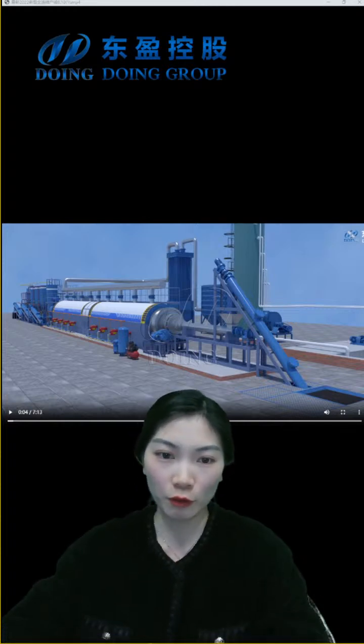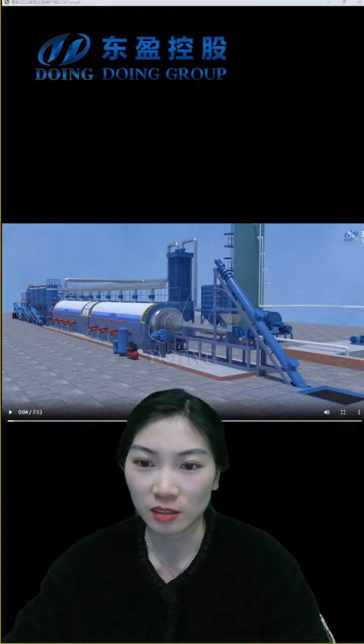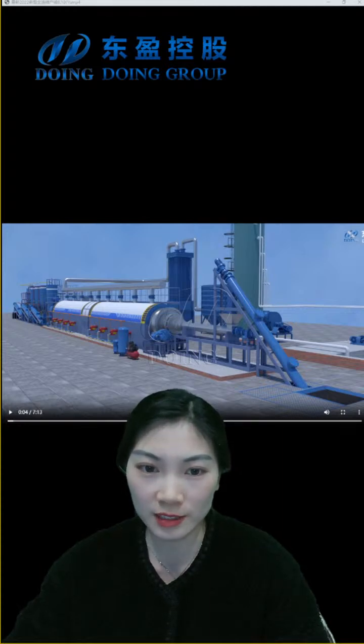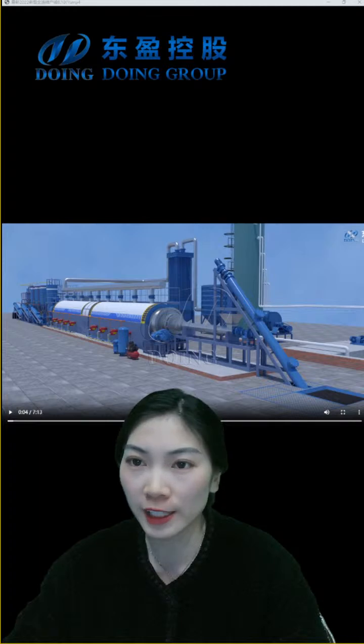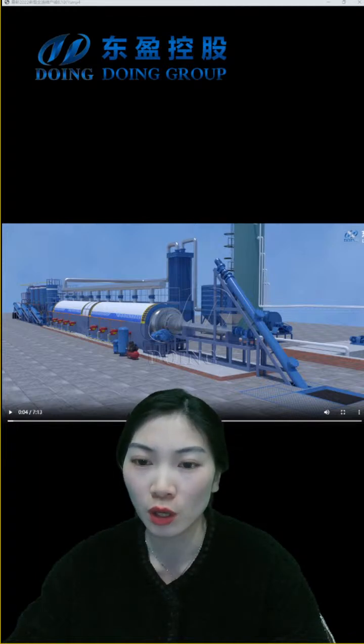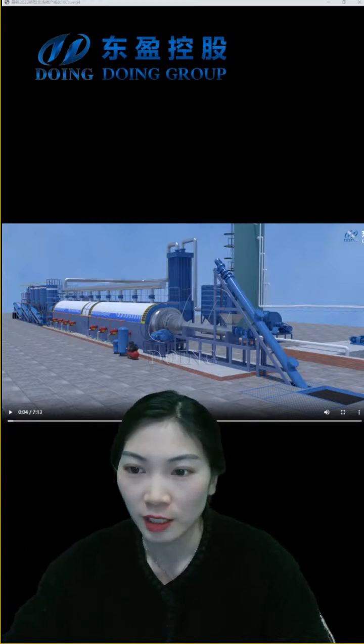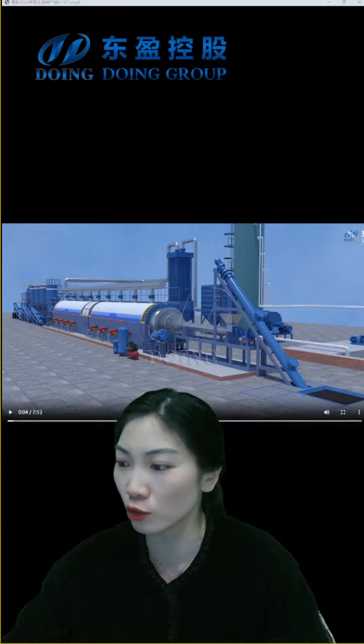For a batch pyrolysis plant, you can feed whole tires or plastic wastes and other solid raw material, no problem. But for a fully continuous pyrolysis plant, you need to ensure your tires are first converted into rubber powder, about 5 mm, with no metal inside or hard issues.